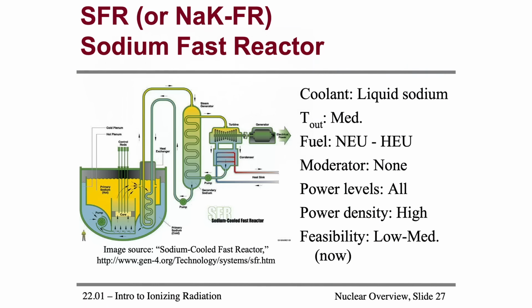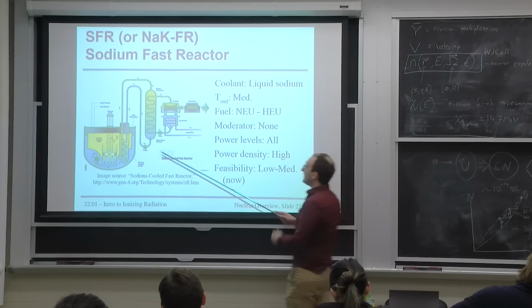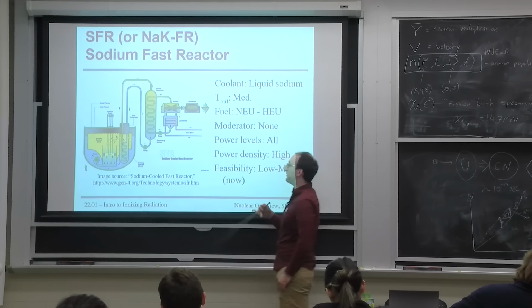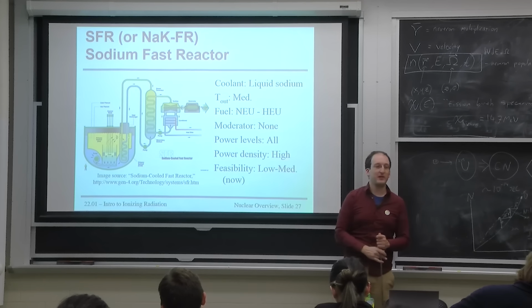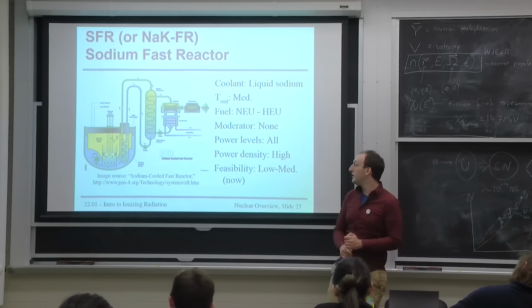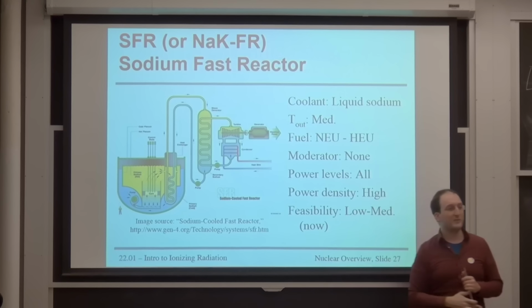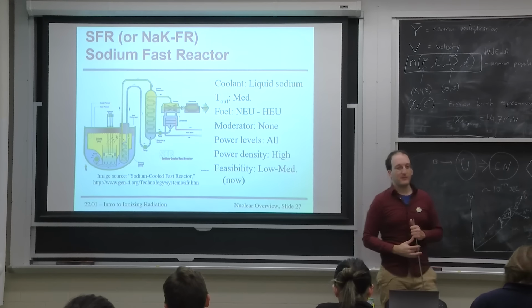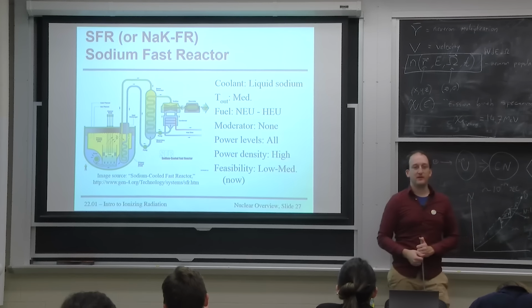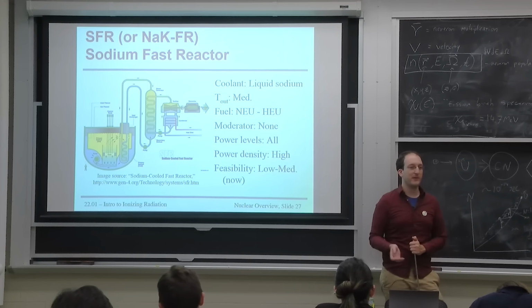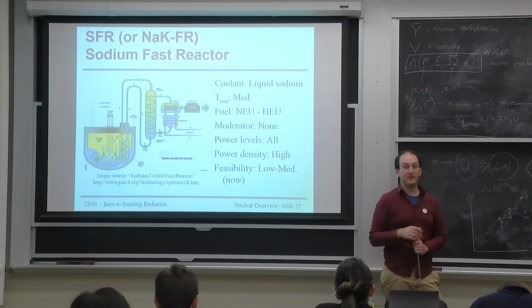So the sodium fast reactor has a number of advantages, like you don't really need any pressure. As long as you have a cover gas keeping the sodium from reacting with anything, like the moisture in the air or any errant water in the room, you can just circulate it through the core. And liquid metals are awesome heat conductors. They might not have the best heat capacity, as in how much energy per gram they can store like water, but they're really good conductors with very high thermal conductivity.